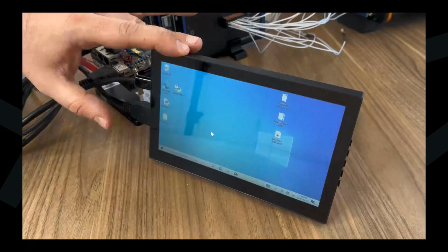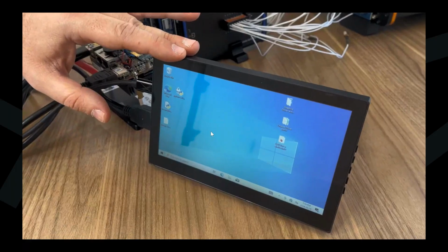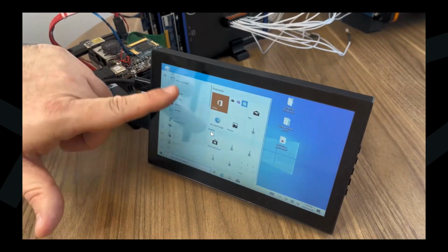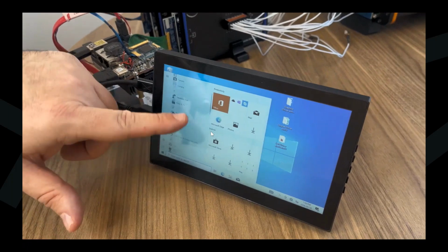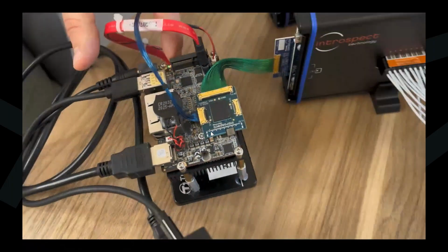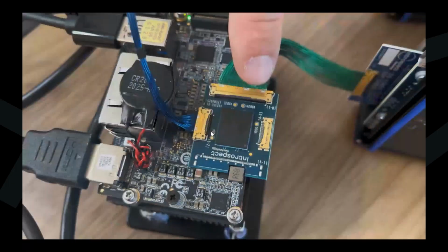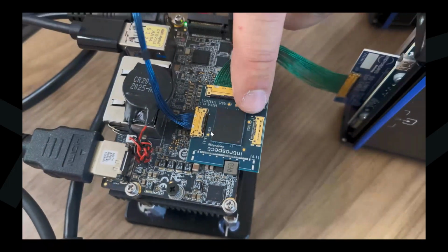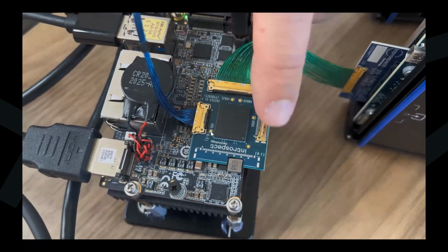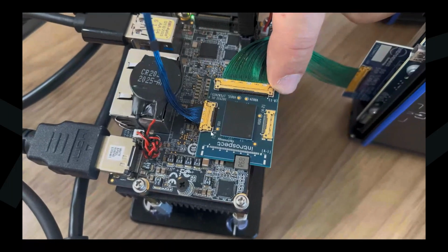So here is a live PC that is based on the Windows operating system and whose architecture is built around LPDDR5 memory. So as you can see, this is a live Windows operating system. We can run any application we want here. But what's special about this particular PC is that we are probing it live with the Introspect LPDDR protocol analyzer. So I'm showing the logic board for the PC here. And of course, of particular interest is the LPDDR5 memory. This is a 315 ball standard package of DDR5 memory. And here it is sitting on top of the Introspect Technology integrated tip interposer.